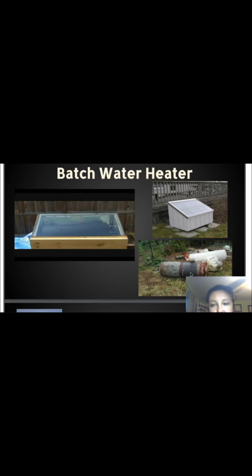So I made sure that I had a tank that had good water retention. I cut off the exterior aluminum lining of the tank and peeled away all of the insulation. You can see my insulation right there, that was in between the two tanks, and basically exposed it. Then I built a nice insulated box for it to go into, painted my tank with Rust-Oleum paint on the exterior, and then I just hooked up my lines. Yep, I ran them up into the house and hooked them up, and I'm good to go.